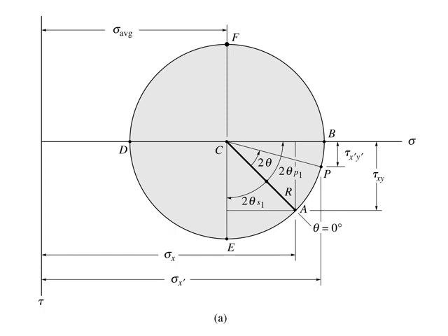All angles are twice the actual angle. So all angles in Mohr circle are twice the actual angle. Now point B represents the location of principal stress 1 or maximum. Point D is the minimum value. So you have coordinate here as sigma 1 or sigma maximum and 0. Coordinate for point D is sigma 2 or minimum stress and 0.